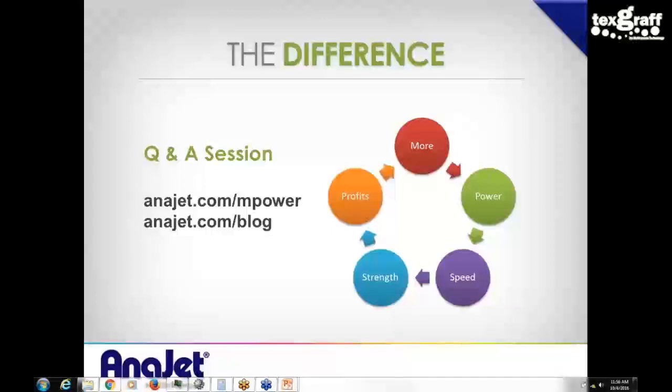Another piece that can play a part is humidity. We're working with water-based ink, so in drier climates, like Arizona or Nevada, the water in the ink will evaporate, making the ink more viscous. Whereas if you're in very humid climates, like down south, Texas, Florida, Georgia, humidity is great for the printer. So if you're in a drier climate, get a humidifier. They're $150 at Home Depot. Stick it right next to the printer and you'll be fine.